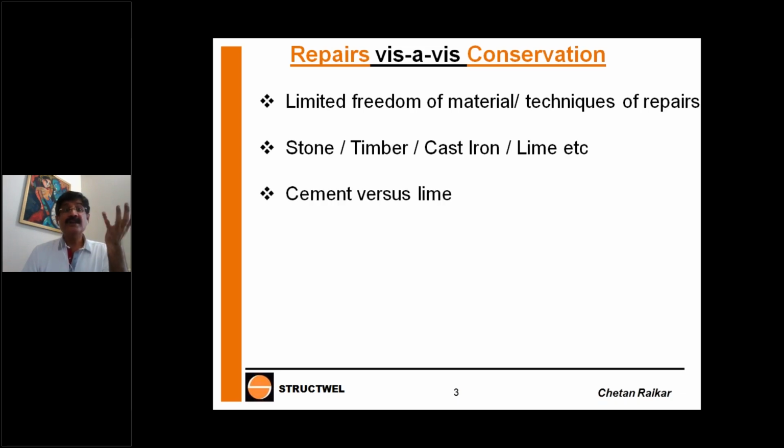Next point, which always comes, is cement versus lime. A lot of structural engineers ask me, "Conservation matlab wo sab lime mein karne ka na?" I said, who said that? That's not true. But you can't be doing pointing or stone masonry with cement. You have to be judicious, you have to be careful, you have to be sensitive towards the needs of the structure when you use cement, when you use lime, or any other restoration material for that matter.